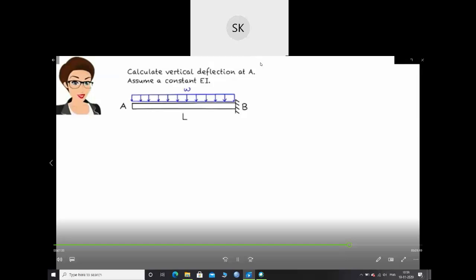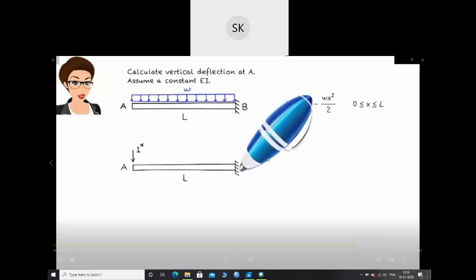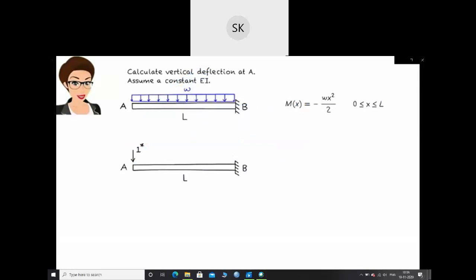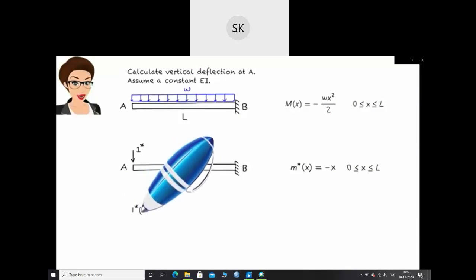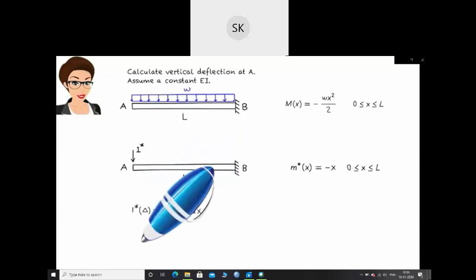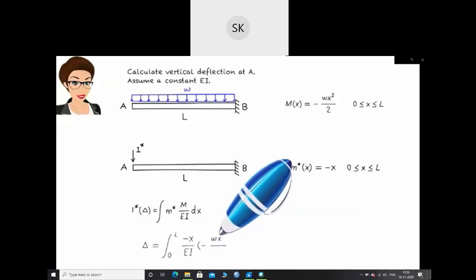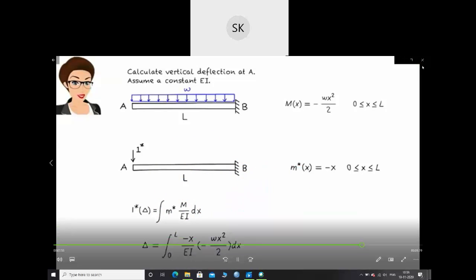We start by writing the moment equation for the beam. Now, remove the real load and place a unit virtual load at A. Write the moment equation due to this unit load. The virtual work method equation is... so the vertical displacement of the cantilever at A is...